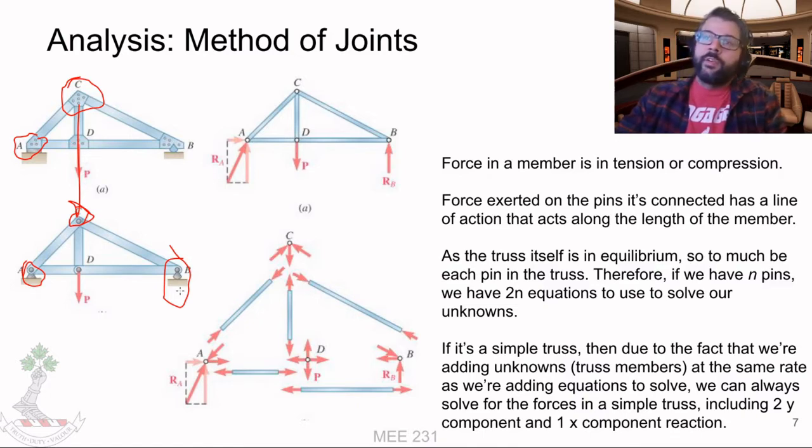Well, not only just so it's a determinate structure, also so that when things get warm or cold, your bridge is going to shrink or expand. Well, expand when it gets warm, shrink when it gets cold, and that can cause problems if you have a fixed connection at both ends. Then essentially your bridge might start stretching apart or crumpling or what have you. Anyhow, that's neither here nor there. We'll be talking about thermal effects next year.